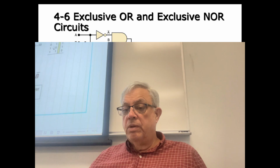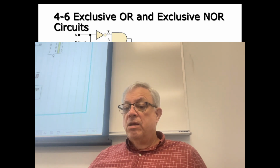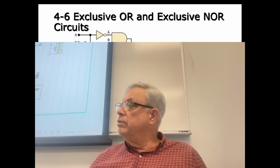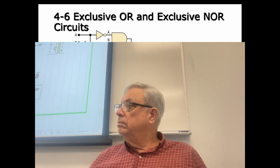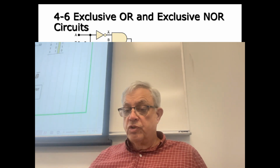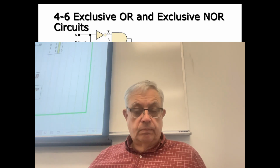If A is 1 and B is 0, I get a 1. What does this mean? This means that as long as I get a 1 out, as long as A and B are different. That's the exclusive OR. Truth output expression, A not B or AB not. And there's the solution.